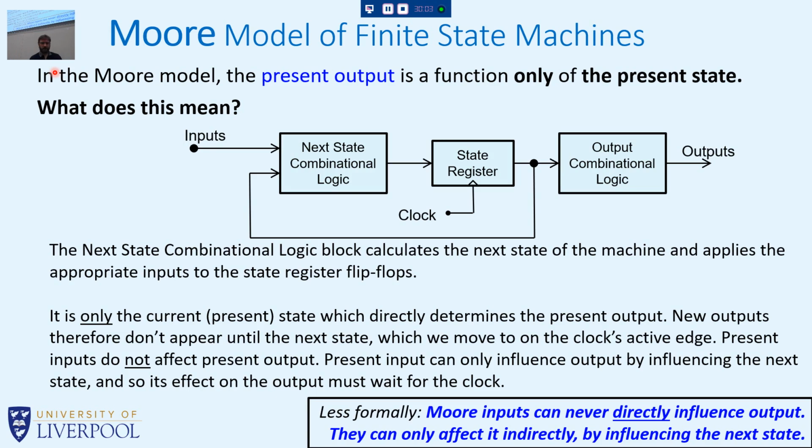Okay, so if we now look here, and I'd invite you to look later, because I don't want to bore the socks off you, we can see some discussion of what this means, but I just want to highlight something from both of these slides, the Moore and the Mealy. What have they got in common? They've got some combinational logic, they've got some sequential logic, which is the beating heart of the system, that's your flip-flops, okay, and they've got some other combinational logic.